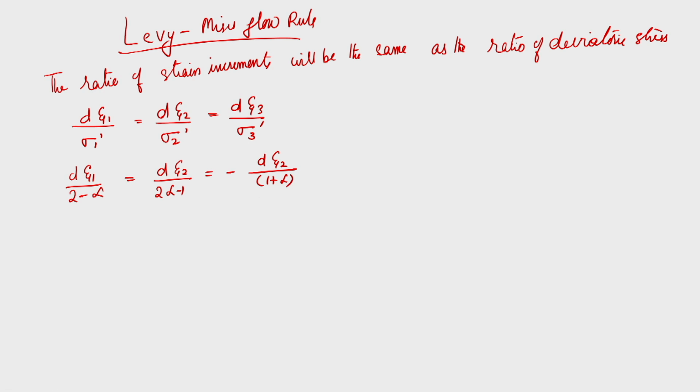And see, under plane stress condition, if it is deforming under proportional conditions in all directions, that means the stress ratio is maintained constant, then we can integrate the above equation and get the strain itself, instead of strain increment.